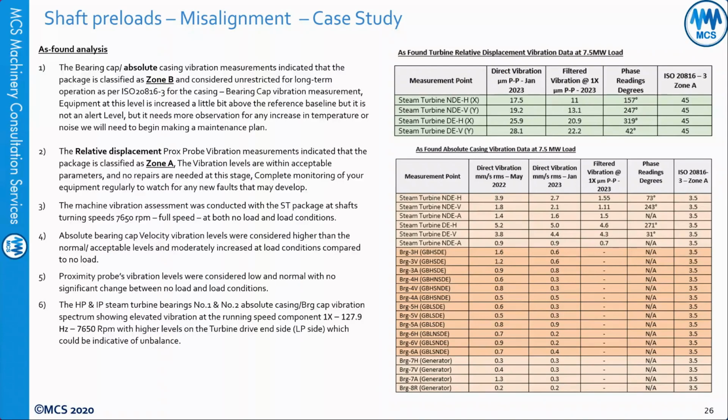So, early on in your presentation, you were on the shaft misalignment. The first question is asking which software is used to draw the center line position in 3D, like you did in this example? This was the Emerson MHM software. The device was the 2600 multi-channel analyzer, and this is the only one I found that can do this.